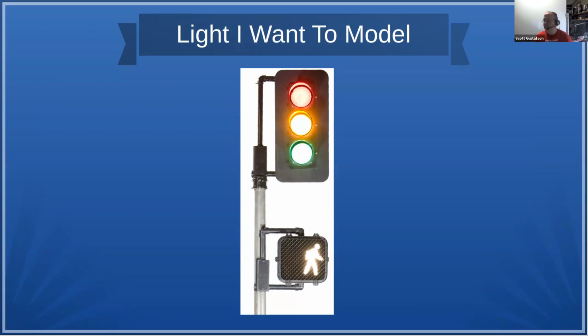Well, there's actually only 4 states in this particular case, because the green light is the only time that the walk and the don't walk are changing. When the green is on initially, the walk comes on. When the green light changes to don't walk flashing is before the yellow light comes on. When the yellow light comes on, the don't walk is solid, and then our red light and don't walk are solid. Anyway, so 4. So I'm really, really close now to making my traffic light.